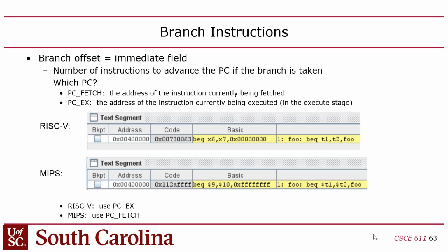And actually, this one doesn't really require a whole lot of changes from Lab 3. The goal is to implement branch instructions, so we have to add support for that. Last time I talked about how RISC-V uses PC relative addressing for branches and jumps, unlike MIPS.